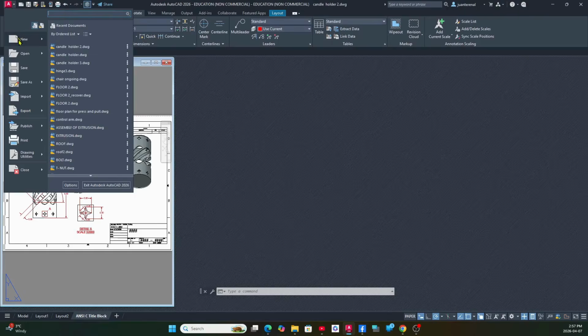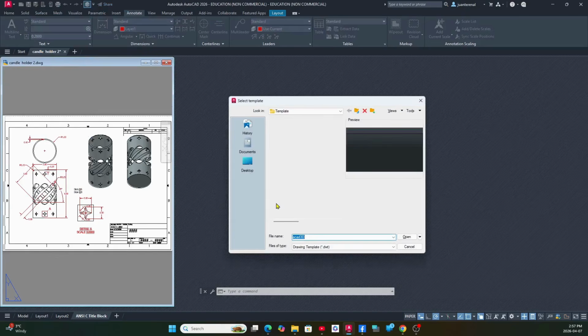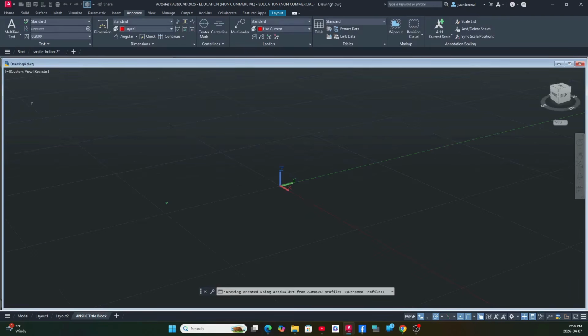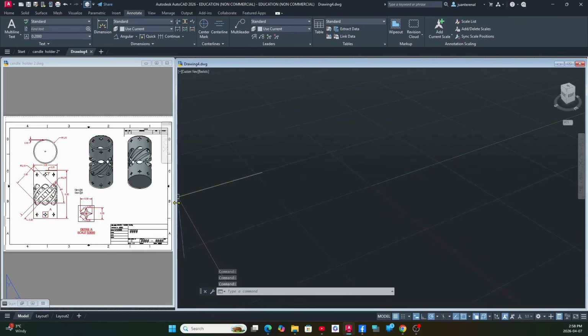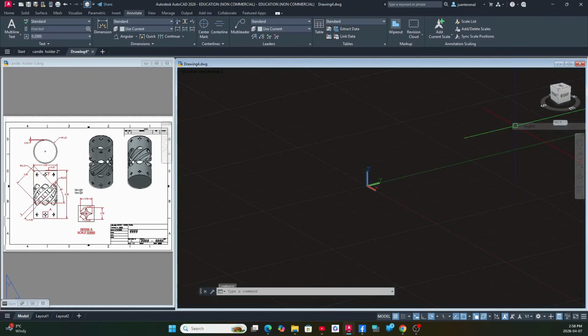by the AutoCAD icon, select New. And since I'm using inches, I'm going to use the AutoCAD 3D template for imperial units and click Open. Just going to adjust my windows and work in parallel projection. Click this drop-down arrow and select Parallel.